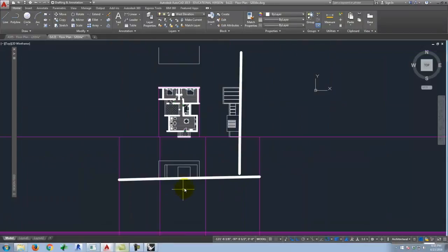Okay? So my goal for you today is to at least get one elevation done. Ultimately, for your assignment 105, you're going to need all 4 elevations, so the more you get done, the better. But we're shooting to get 1 elevation done. Remember to turn all your layers on if you decide to rotate them and not draw them upside down. If you want to do a sloping roof on top of your building, that's perfectly fine, but I would recommend establishing your basic elevations first with a ceiling height of 8 or 10 feet, maybe 12 feet, depending. And then after you've done your elevation as kind of a flat top, then we'll come back and add your roofs to it. Okay? But I don't want to sit here and have you keep listening to me any longer than you already have. All right?